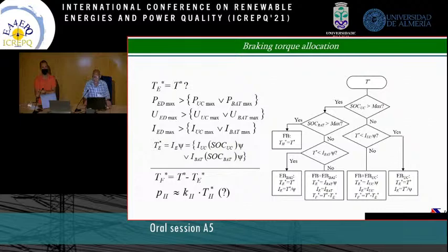So the electrical system is very powerful, but it has many limitations as compared to traditional hydraulic friction. This is why our algorithm estimates all the sensors, and in the case of impossibility to use fully electrical braking, our system applies electrical plus friction, or only friction as the final case.